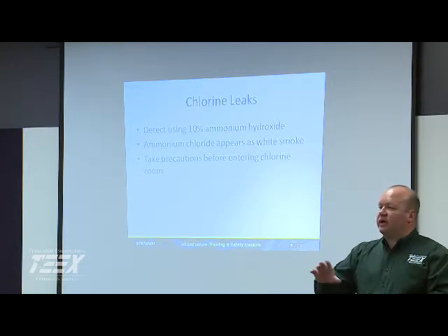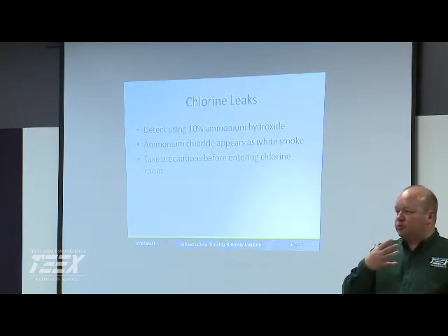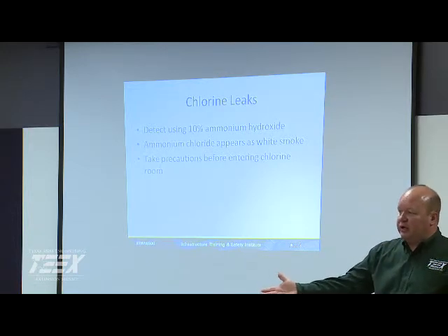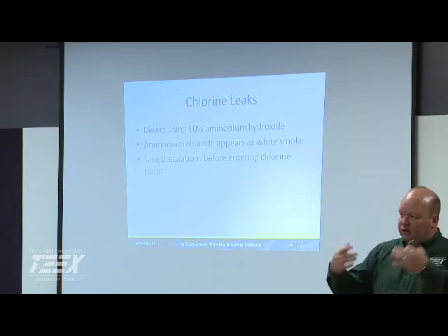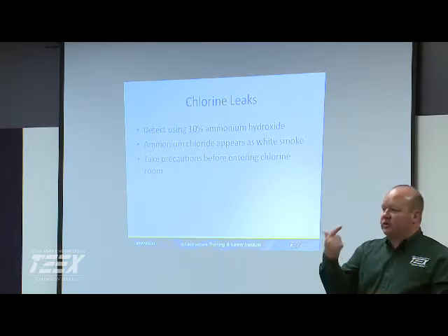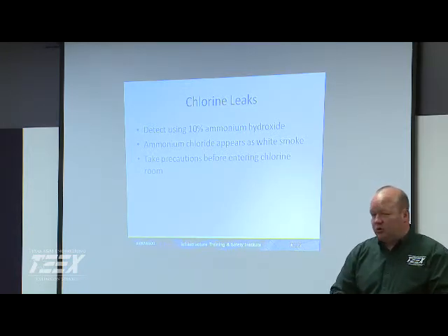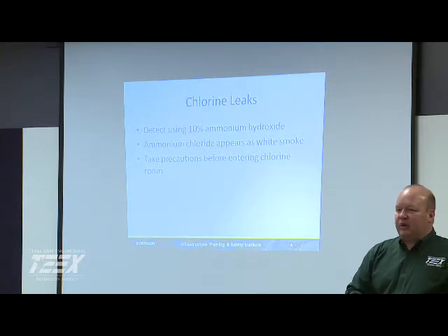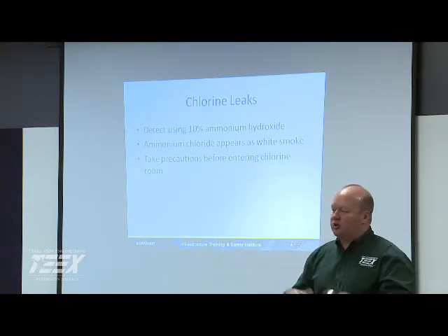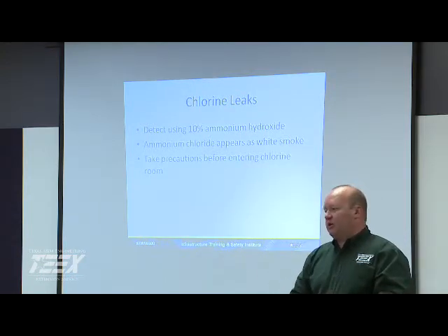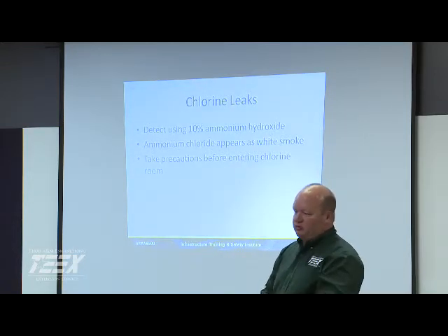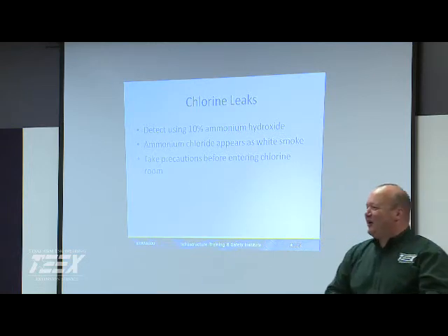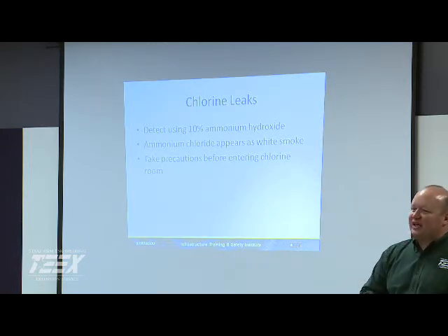Yeah, and I agree with that, because if you have a respirator, you can't go in and repair a leak. But if you're in there doing a changeover and you have a leak, it gives you the chance to get out without being exposed to it. But yeah, I wouldn't recommend somebody go in, because you're going to use up that cartridge in a heartbeat with a high concentration, and now it's bypassing, and you might as well take a hit off of the cylinder or the container or something.